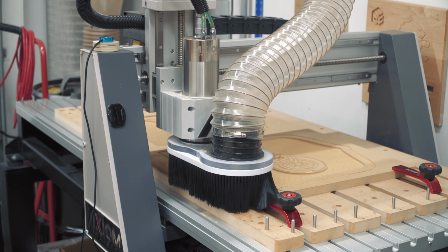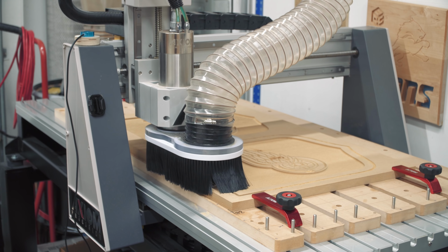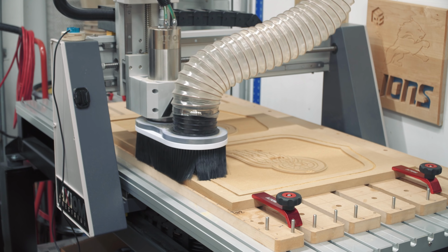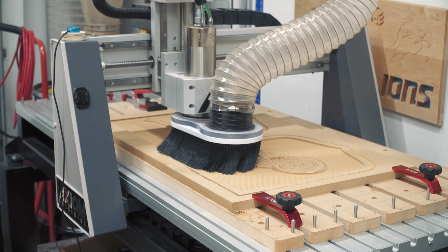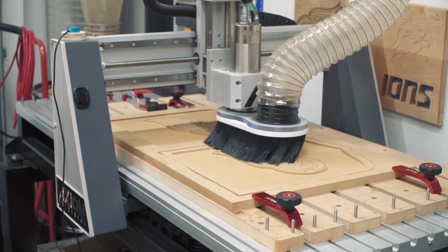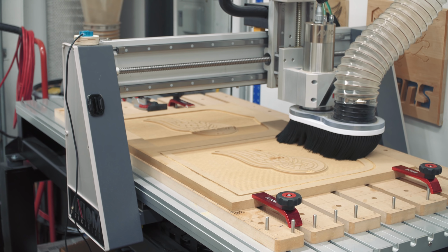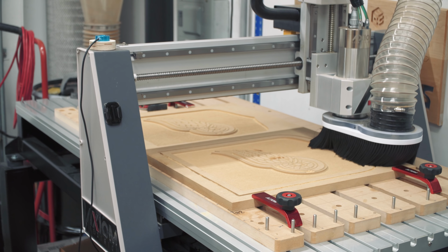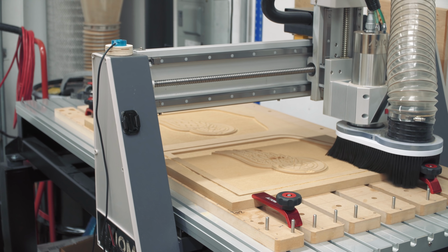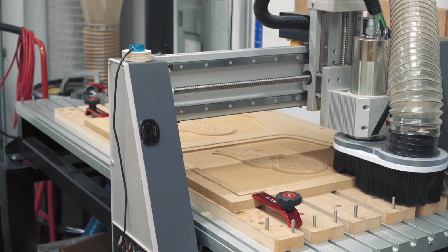And you'll notice a few oil spots on the signs, and that's because I added too much oil to the ball screws before running this project, and it eventually dripped onto the material. Just routine maintenance. You're supposed to keep the ball screws lubricated. And I'm hoping this won't be an issue at all. I'm going to scrub it and seal it with shellac, so I don't think it'll be an issue.